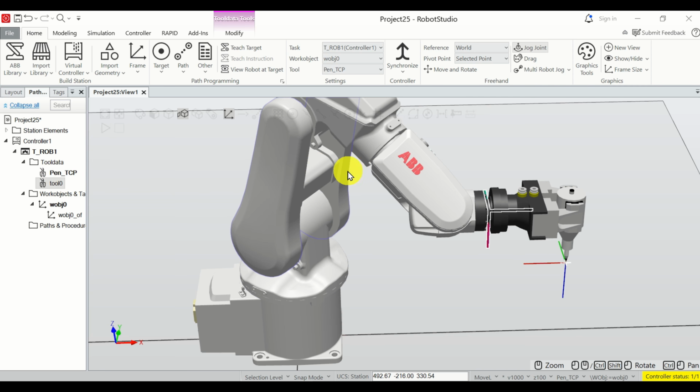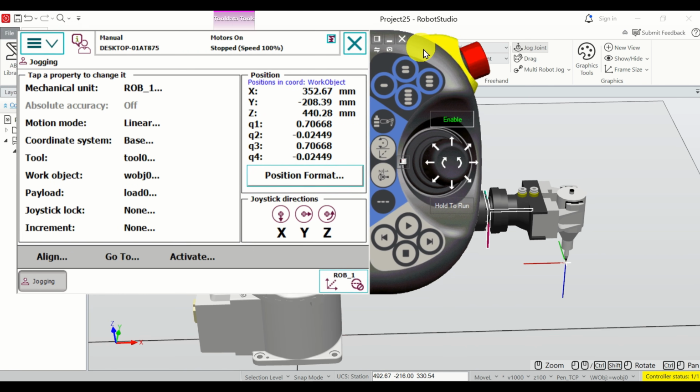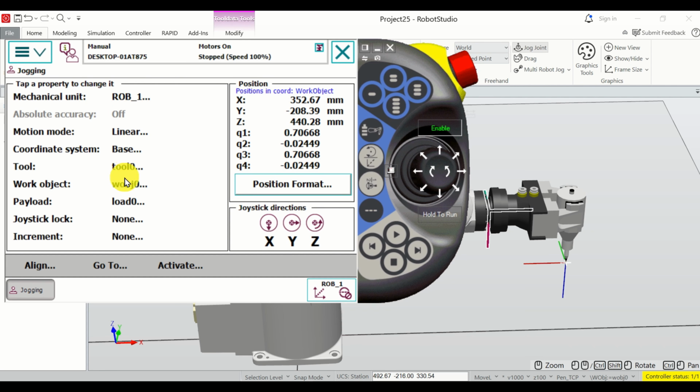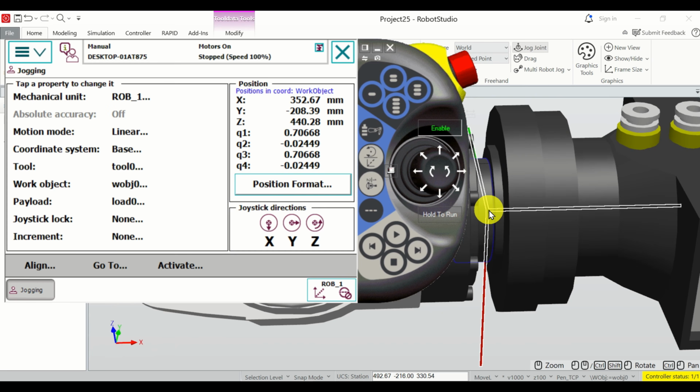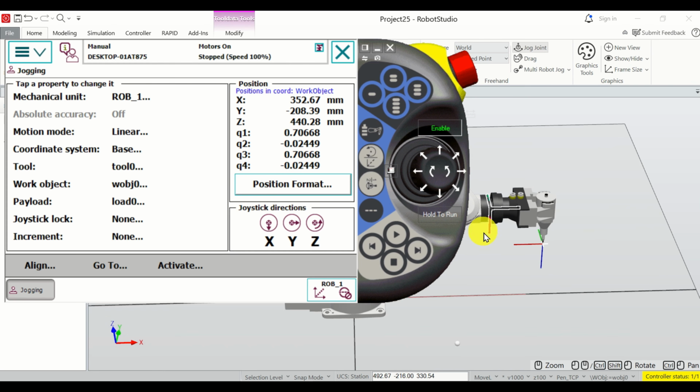However, if you're playing with a real robot, then you will have to do experiments, and I will show you how to do that. So over here, we have tool 0. Now, let's bring back the menu over here, and let's see what is written over here, tool 0. Okay, so this means that we are actually moving, or better to say measuring, in x, y, and z coordinates this point over here. That is the center of this coordinate system attached to this plate over here.